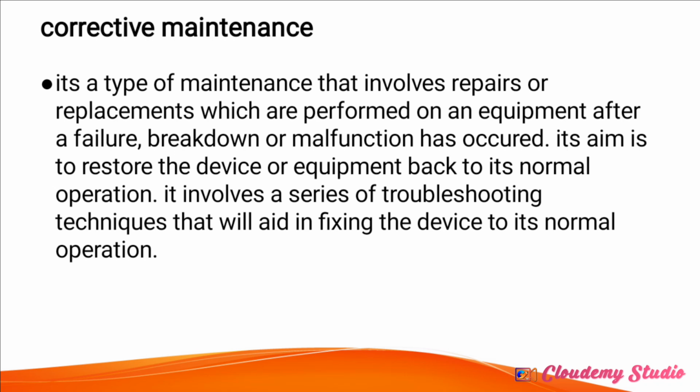If it's an installation, you've gone to a site, it's an installation that has been performed, and you discover that all the sockets are faulty, all the switches are faulty, the consumer control box is faulty, the lighting system and the socket or the cooker system is faulty, there's no way you'll be repairing that system, because 85% of that system is faulty. So what you'll be required to do is replace.